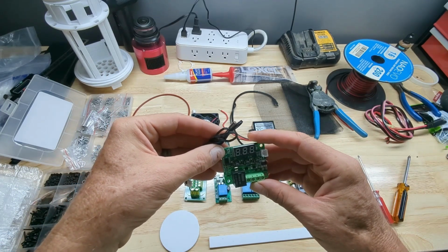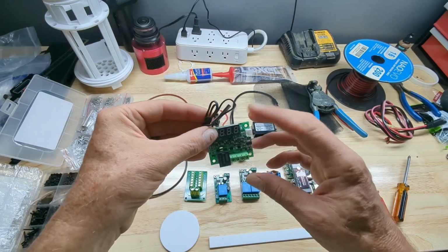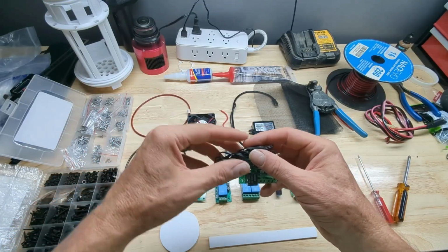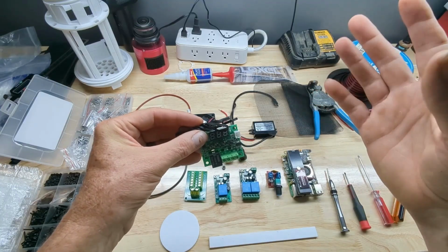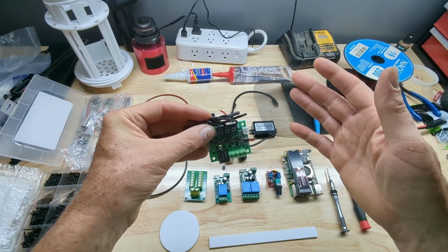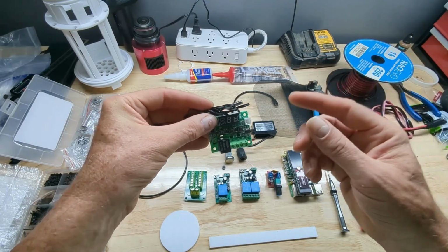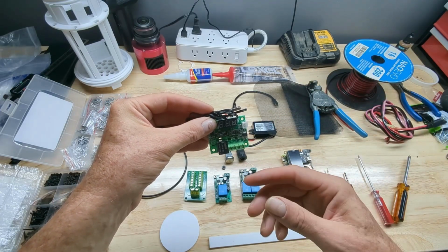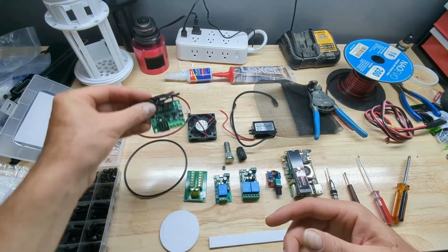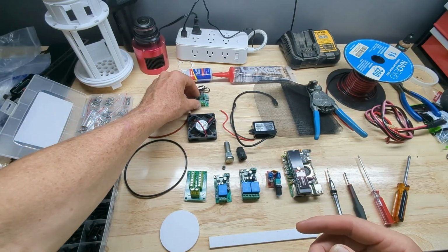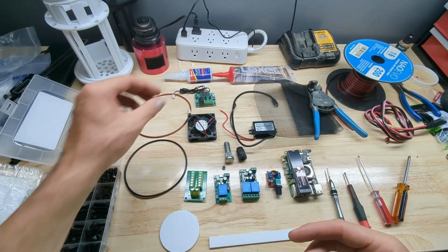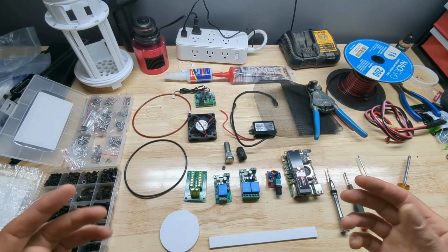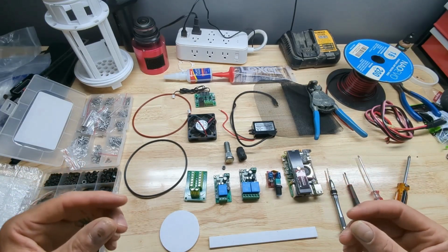So if it gets above 100 degrees, this little thermostat kicks on and turns our fan on. This little fan that we have here, it will turn on after it reaches whatever temperature. Say we have the threshold set at 100 degrees or 110, it'll run until it gets all the way back down to 95 degrees, and then it shuts off. And it just repeats that process all day long. Now, there may be certain days where it's extremely hot outside, and once it turns on, it doesn't turn off until nighttime, but that's fine. We're keeping airflow running through there and keeping everything overall cooler in the box. I won't say cool, but cooler.